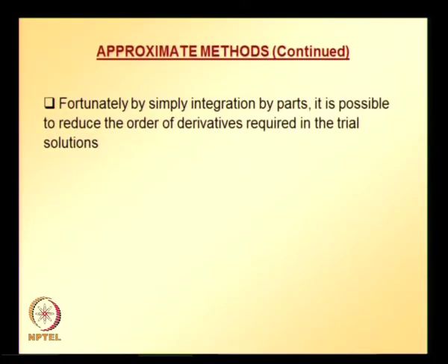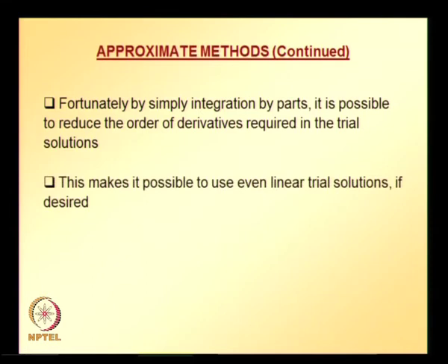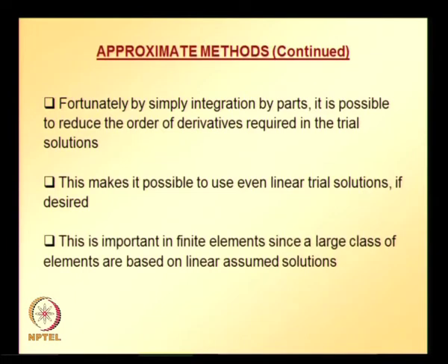Fortunately, by simple integration by parts it is possible to reduce the order of derivatives required in the trial solution, and this makes it possible to even use a linear trial solution if desired. This is very important in finite elements, since a large class of elements are based on linear assumed solutions. This point will be clearer at later stages of this course. So, now let us look at how to proceed.